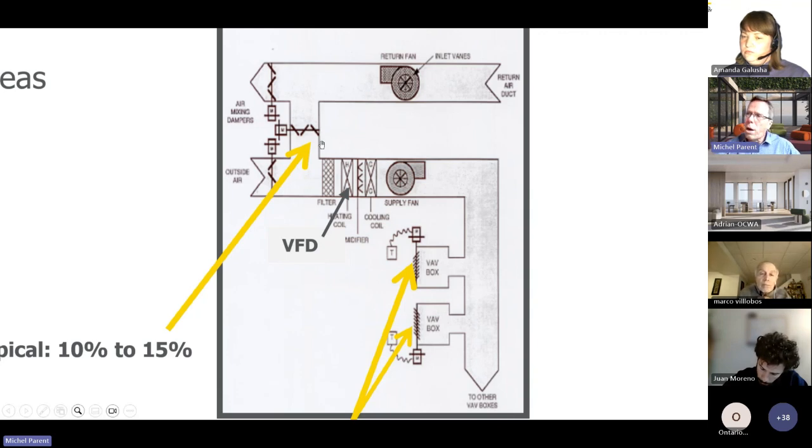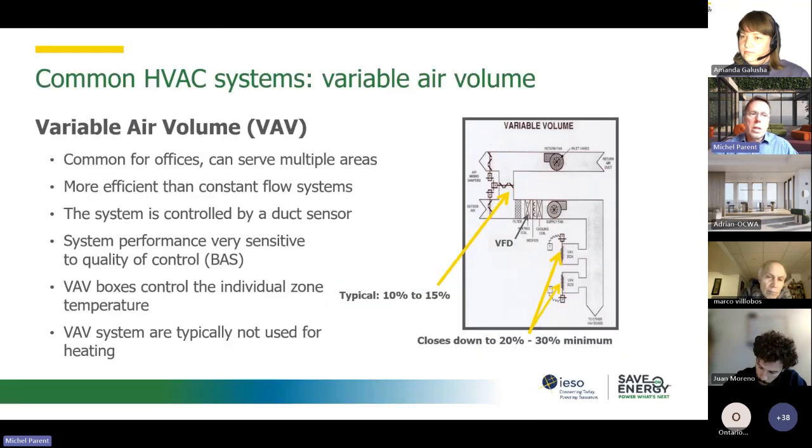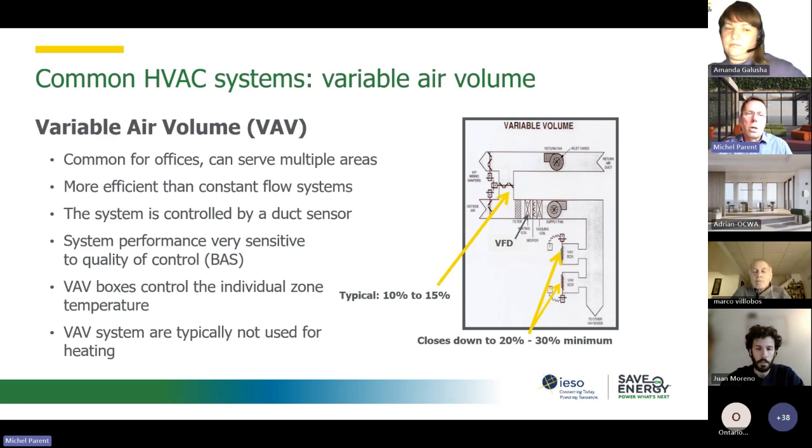So, and also have a look at your dampers. Always look again at the dampers. What is the minimum position for those dampers? And what you'll see is a percentage opening, and again, it is not equal to the percentage of outside air. So that's the three types that I wanted to present, and the influence of those configurations will be more clearly shown in the coming slides.